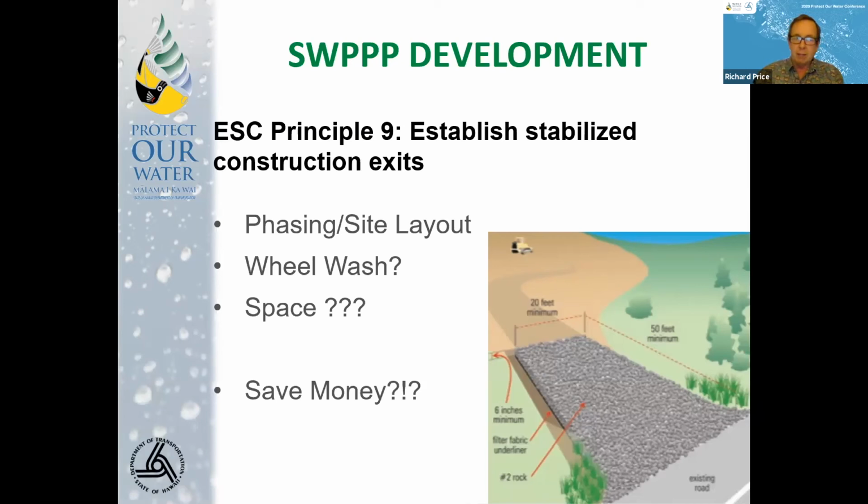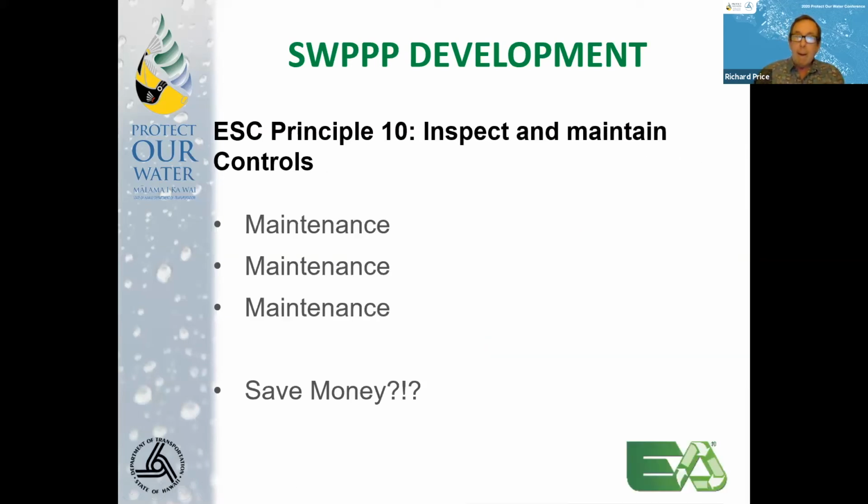There are some really nice wheel wash systems out there now, and you may find, depending on the size and the duration and the amount of traffic at your site, that having a wheel wash in front of your stabilized construction exit can avoid getting a lot of that sediment into the gravel that then causes you to have to dig it all out and replace it. And I know space is always a confining factor on these as well. But I think there is some potential to look at that.